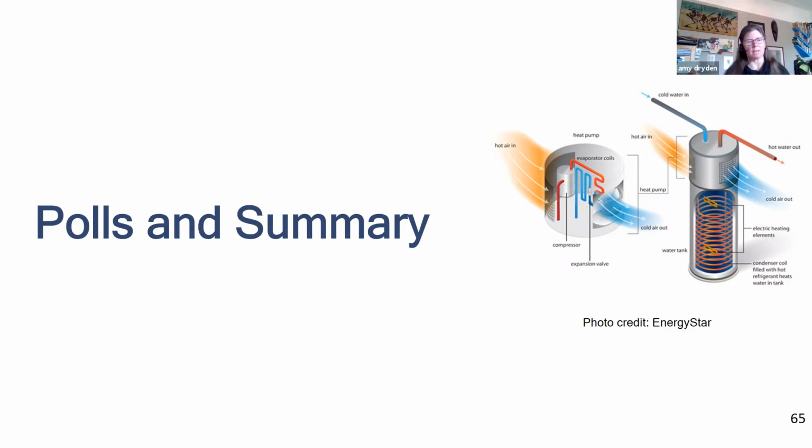Then we're also thinking about load shifting, which is becoming more important, and you'll hear more about it, where we want to reduce our energy use during the grid peak, that 5 to 9 p.m. period. So if I think about my water heater as a water battery, and I'm heating it up to 140 and not drawing down until later, I get to reduce my call for electricity during that grid peak. So that's also a benefit.